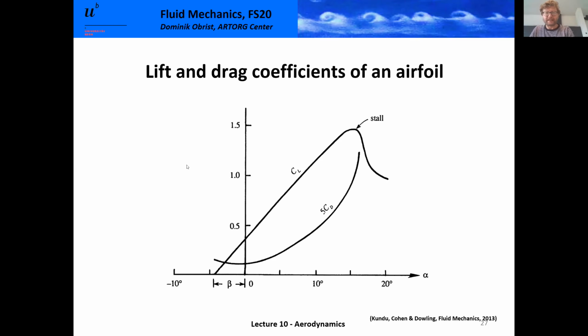And you will actually find that the lift coefficient, now we're going back to this coefficient thing, for an airfoil, CL, is, to first order, proportional to the angle of attack. So you increase the angle of attack of an airfoil, you will linearly increase the lift coefficient.